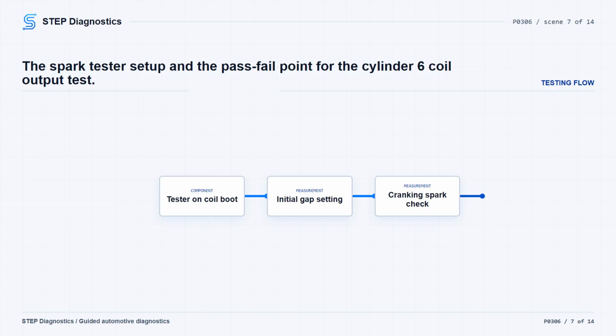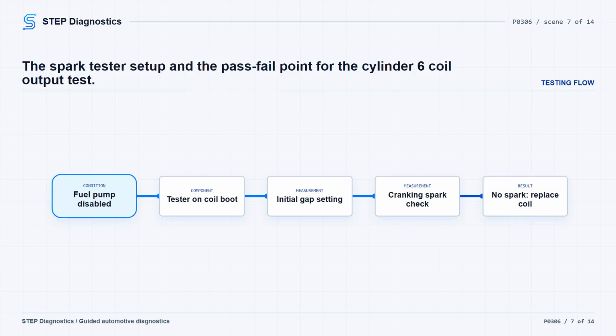If the ignition path is not narrowed to one cylinder, use the same spark test setup across all cylinders. There is also a component inspection variant for a different engine family, but on this 2.7L path, once spark is present, continue with the spark plug checks. Remove and inspect the spark plug for damage, wear, carbon tracking, deposits, and correct gap. Then,